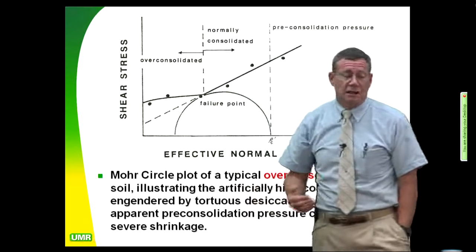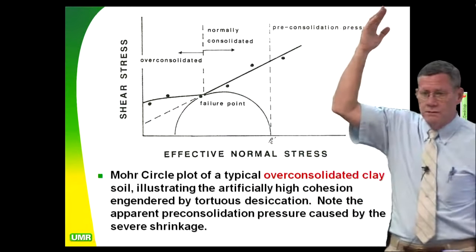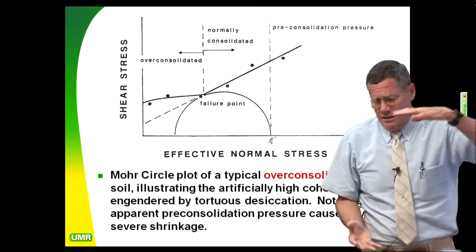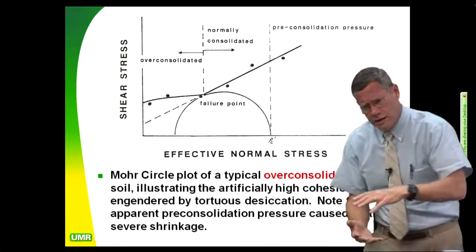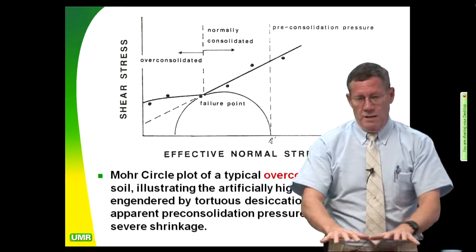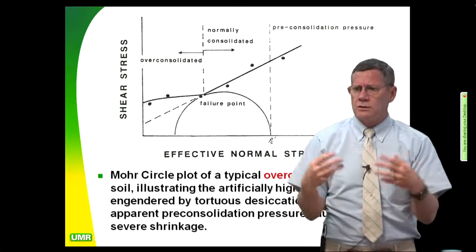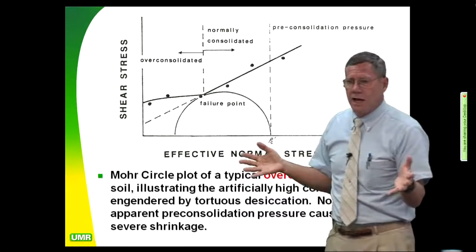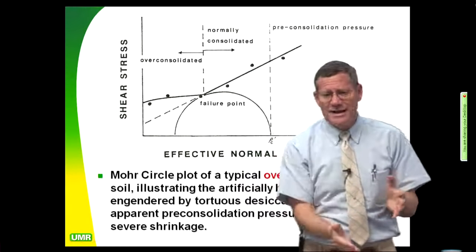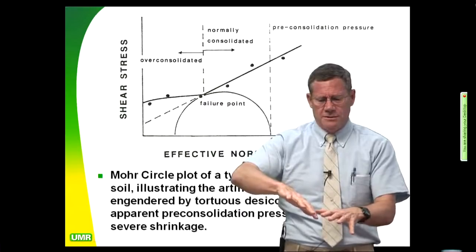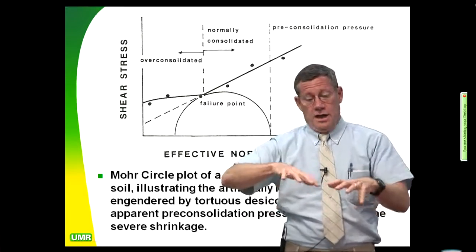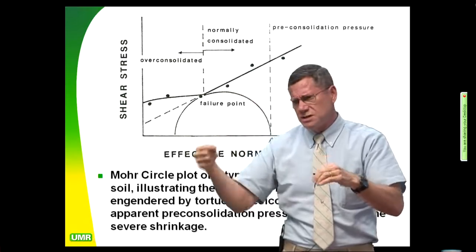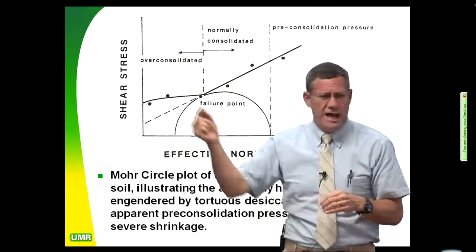Now, you get to places like Cleveland, where they had glaciers 3,000 feet thick going up the Cuyahoga River Valley. That's really overconsolidated clay. So that clay has had this huge load on it that's melted away into Lake Erie, and now that clay can rebound with the removal of that glacial load and absorb more and more water. And it's stabilized for the environmental conditions to which it's subjected today. And everything's fine till you make a cut in it. You go out there and make a cut, now you rapidly unload it in a couple hours, and all of a sudden it's going to heave, absorb moisture, and start moving around on you. And once it starts getting a slip surface, you can actually see 80% strength loss. That's scary. That's what happened in the Panama Canal with the Cucaracha Shale.